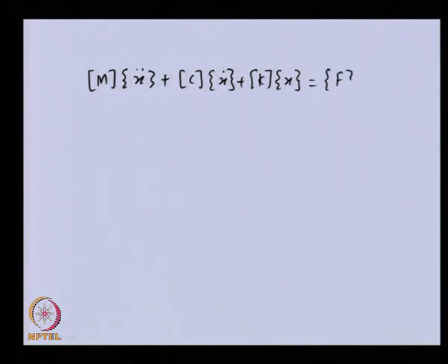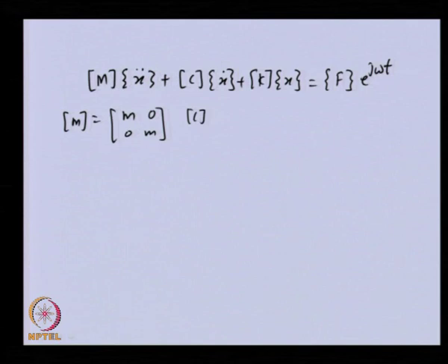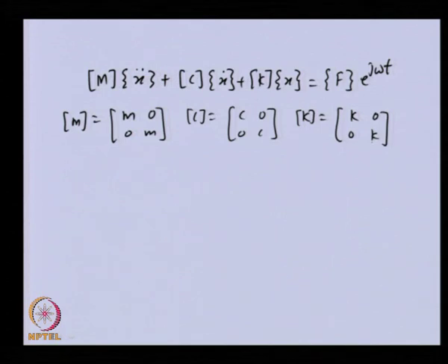The force amplitude and the j omega t time-dependent term are outside, where we have the mass matrix defined earlier as this, the damping matrix as this, and the stiffness matrix K. Diagonal terms are there in all of these. The unbalanced force has unbalance in the x direction and minus j unbalance in the x direction, because this takes care of the 90 degree phase.